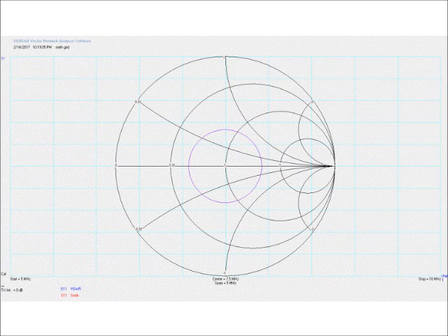And if it's right smack dab on this line, it's perfectly resonant at the frequency, and this is your feed point impedance. Right there's 50 ohms. I can never keep this straight. I can't remember, 72 ohms here or here. But the bottom line is, it's perfectly resonant at the frequency that you're using it on.